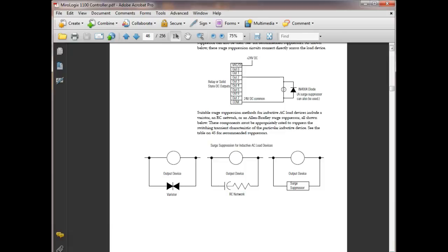So you can tell the difference with AC coils and DC coils right off the bat. DC coils are going to have a lot of wire because that's the only way they get their resistance. What determines how much voltage you get out is the strength of the magnetic field that you have in there to start off with. Then the next thing that determines it is the speed of the motion, and the number of turns of wire. So this is why you get such a big kick out of DC coils when you turn them off, and they will wipe out solid state devices in a heartbeat if you don't suppress them.